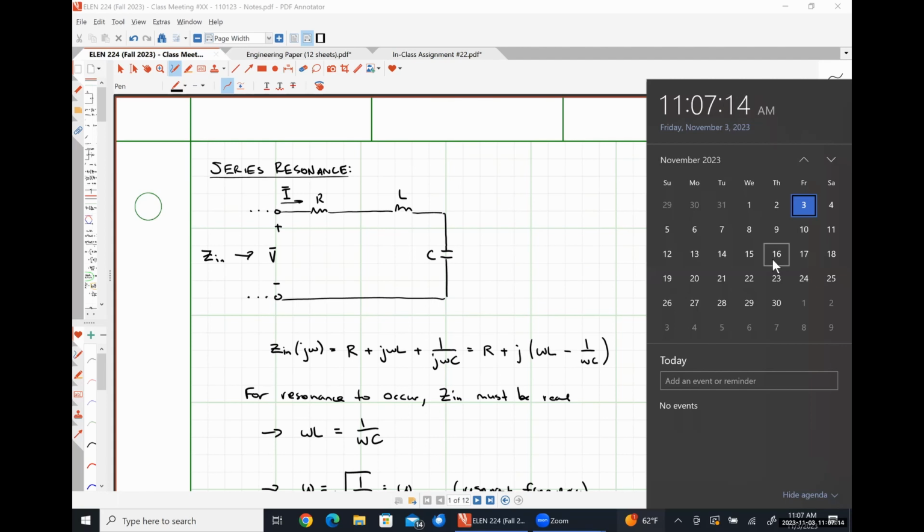Yeah, and then if it happens to work out that you're not scaling, like you don't wind up getting the right magnitude, put a third stage in there that just gives you a gain of whatever it needs to get to that with no phase angle. So that would just be a resistor biased op amp network. From where I put it, I gave you 1 pole and 1 zero, so the negative sign should cancel out there. So you would have a positive signal, so you would use a non-inverting amplifier if you needed to scale. There we go. That sentence just did a third of your design problem.